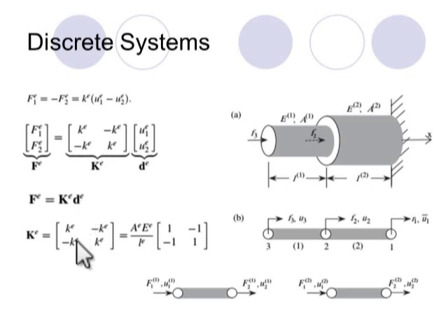If we write the expression for the stiffness of the truss element into its place, we obtain this expression: area multiplied by the Young modulus divided by the initial length of the truss element, because it is commonly assumed that the area of the truss is constant along its length.